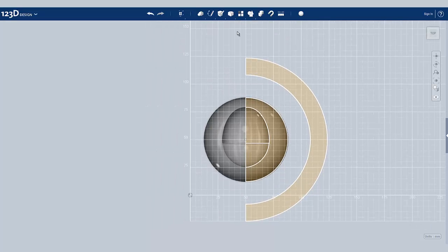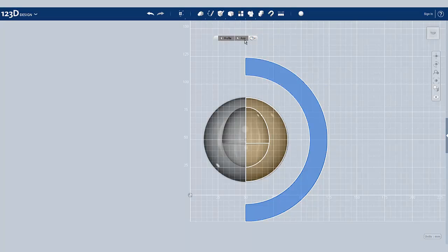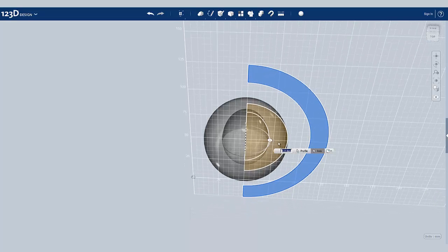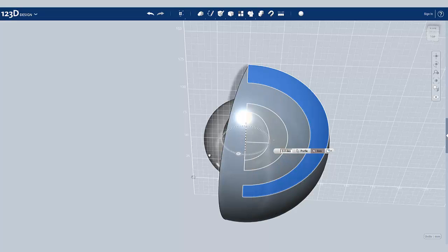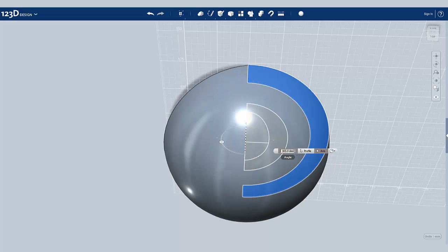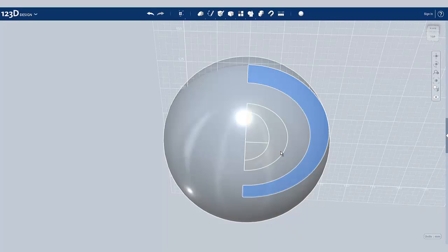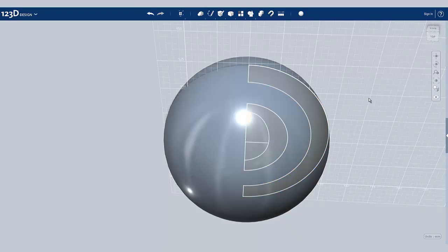Now we're ready to use the Revolve tool again. I'll select the new shape of our profile, then I'll select the same axis as we used last time. Then I'll just go ahead and revolve this by 360 degrees. I'll push enter, and we have our solid. There we go. Now our model is completed.